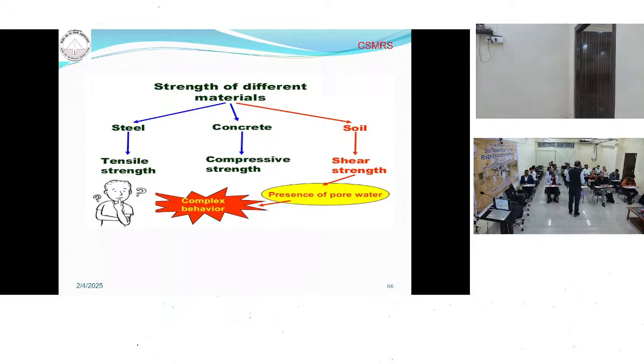Basically, you know that soil has different properties, but as I told you, to complete the consolidation, it takes a lot of time. So if you know the basic properties and index properties, from that you can guess some values, like the Cc value and other things. But to know the exact value, you have to analyze. Those are empirical values, and those values are also site specific.